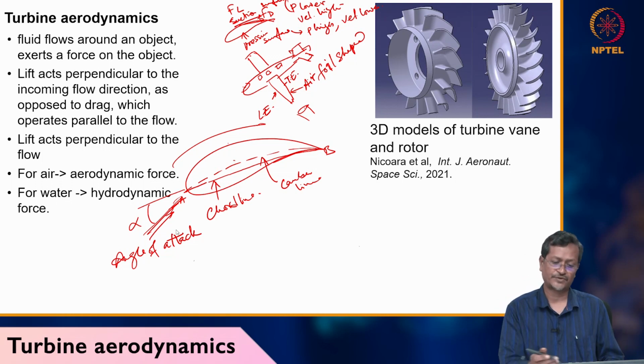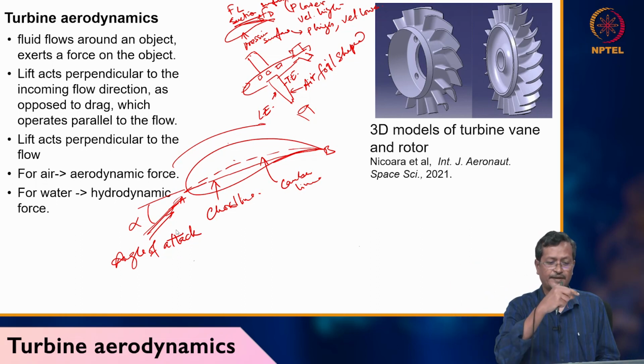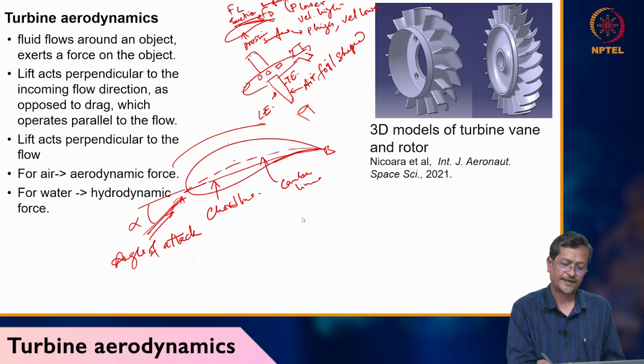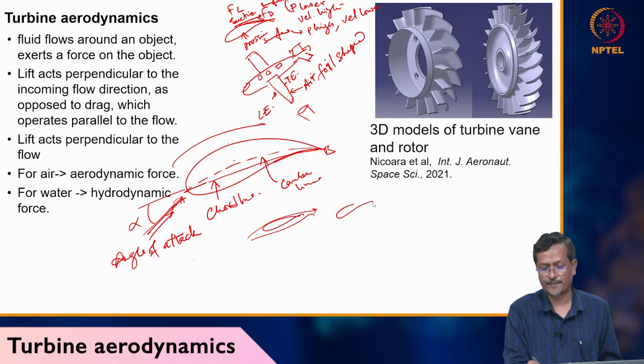What is flow separation? Flow separation is what happens whenever an airfoil is moving in air or air is moving over an airfoil. Both are the same actually. Let's say initially my air is like this, touching the whole surface, with no flow separation. But my angle of attack increases, or flow velocity increases at a very high rate. So what will happen? The fluid will be moving, and at a certain stage lots of vortices will be created. So this is flow separation.